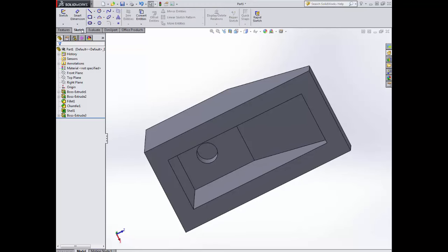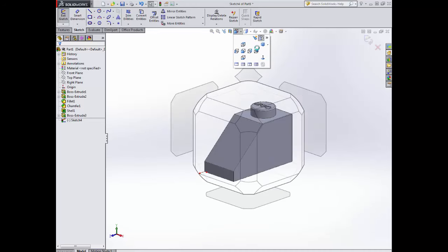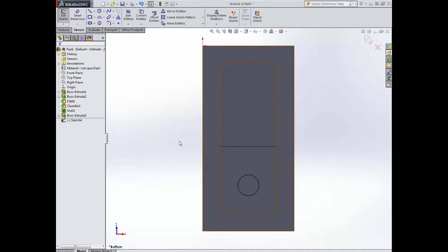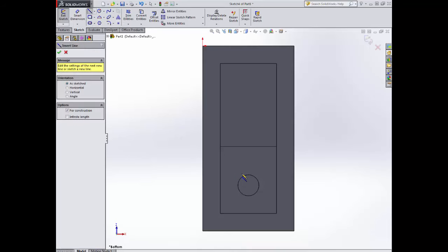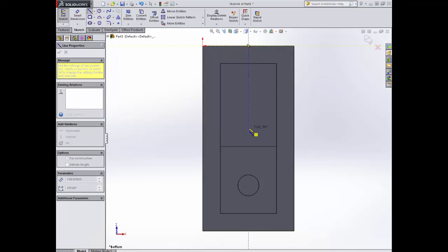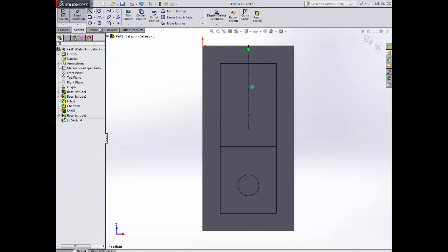Right, I'm now going to sketch the interior. If you look at the orthographic, you can see that there is a cylinder in the middle which allows the Lego blocks to be put together. First thing I need to do is, again, a centre line. What I want to do is work out where the middle of this bottom edge is. Now, my block is currently upside down from the version of the orthographic, so I've got a choice. I can look at the measurements, go from the bottom, or I can make my life easy and use the 8 at the top here, rather than having to do any math.